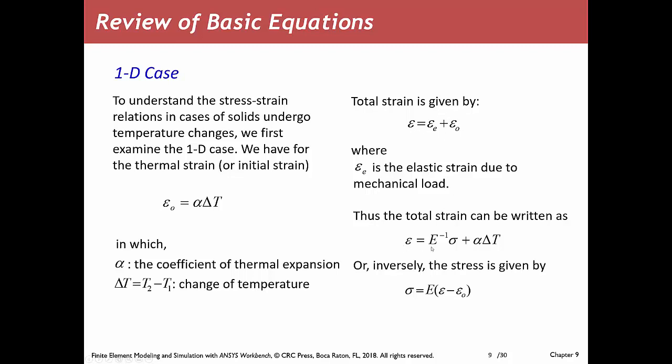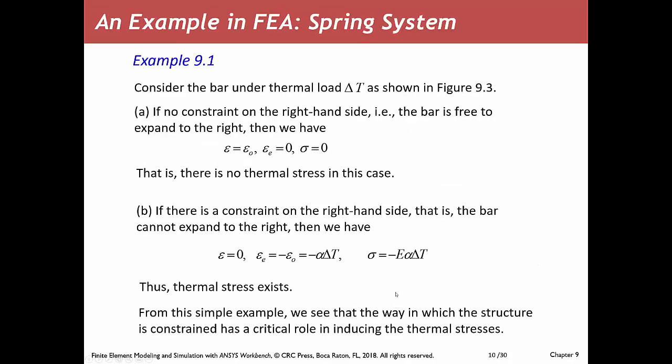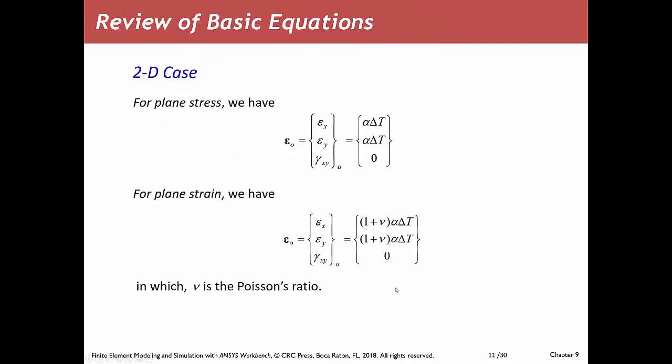So basically, the strain is equal to sigma divided by E, from Hooke's law, sigma is equal to E epsilon, and then the thermal one is equal to alpha delta T, right? So we can write that sigma, if we take this equation amplified, is equal to E times the strain minus the thermal strain. This is the equation, right? And these are examples again available in your textbook, just theoretical examples showing you the calculation when the strain changes. And of course, you know what Poisson ratio is.